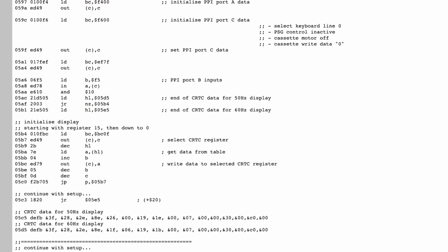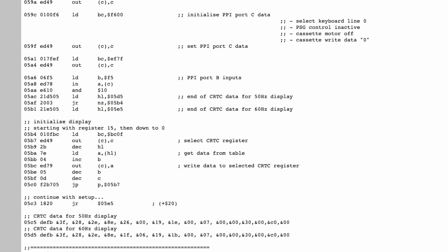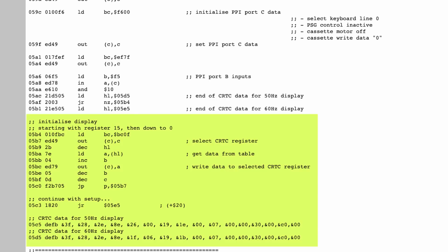Actually, before replacing the CRT controller, I realized there may be another reason why the frequencies are off. The CRT controller can be programmed to work in many different frequencies, and one of the first things the Amstrad does whenever it starts up is to initialize the CRT controller. But if for some reason the ROM was corrupted, it would fail to initialize it, and we would be stuck with some default incorrect frequencies. And that would make sense too, because horizontal sync and vertical sync look to be fine, they're just too slow.